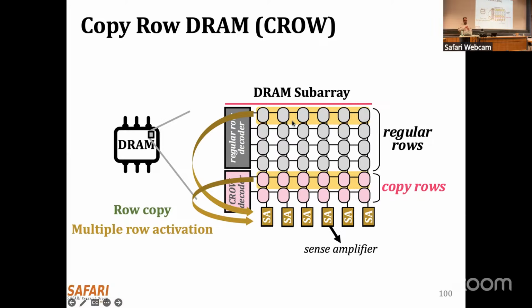Since the data is placed in both regions, they can amplify and provide current to the bit line together. You have two instances of the same thing, and you can activate them separately because they don't share the same decoder. Both of them provide current and amplify the bit line together, and that can give you better performance. Make sense?